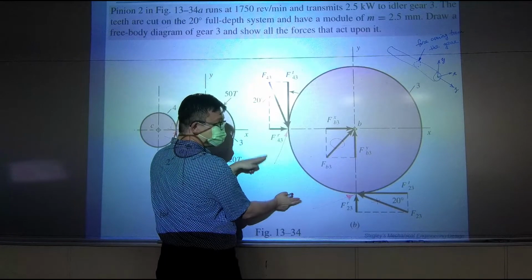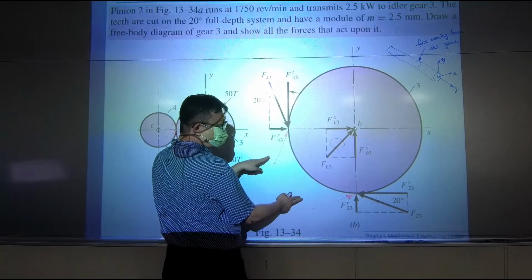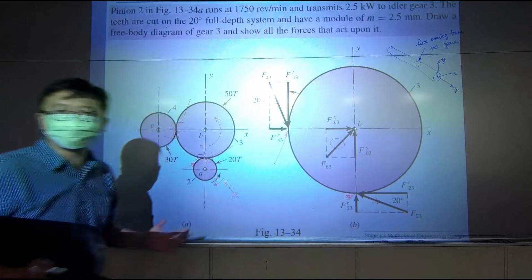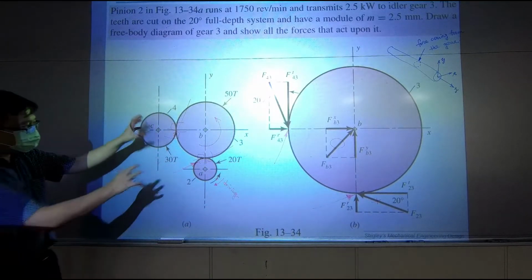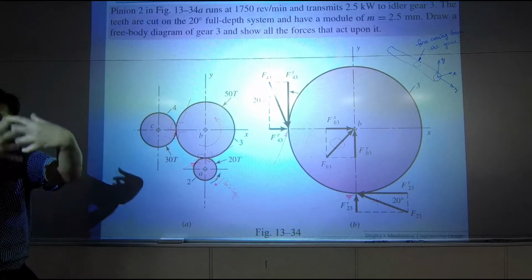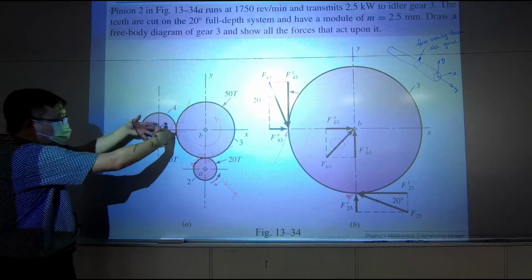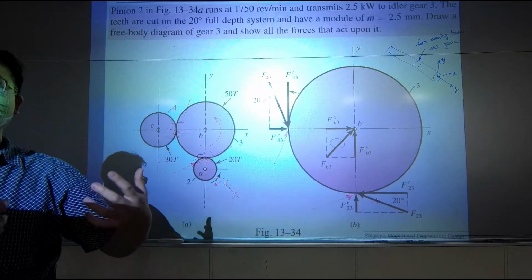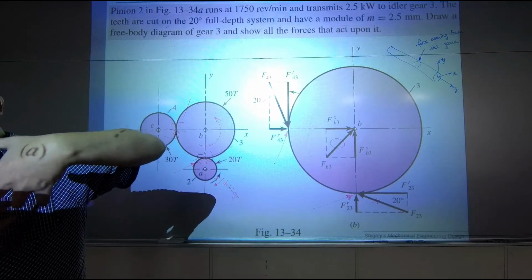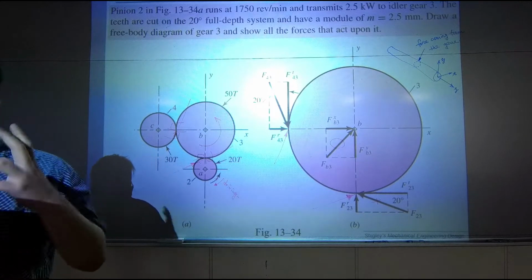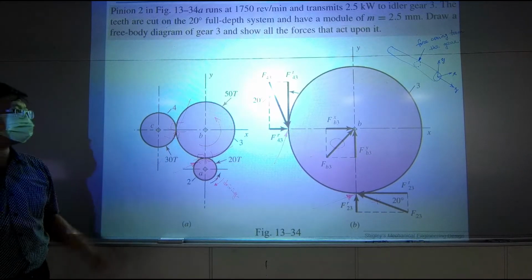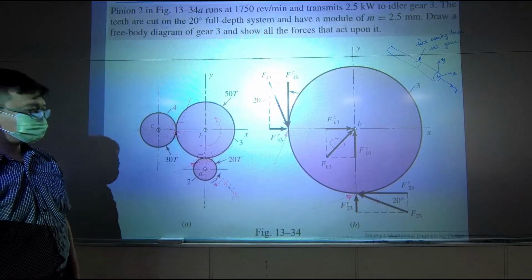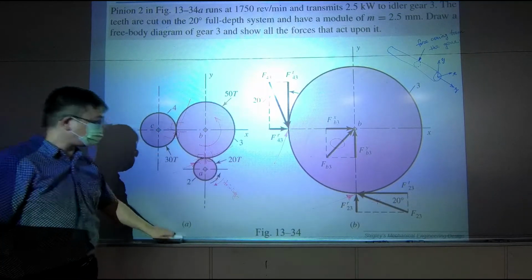those two are important. If you define those two in a wrong orientation, then it's completely wrong. Okay? So the conjugate relationship between the teeth from both sides, and whether it's rotating clockwise or counterclockwise, really matters. Okay? It affects the direction of the external force. Okay, so those are for your reference.